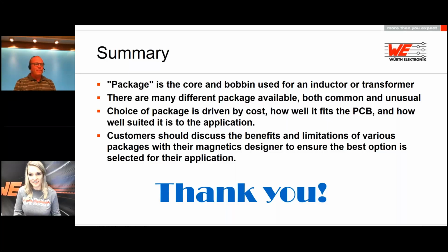I think it does. A few more questions coming in, and then we can wrap everything up. Our next question here: which does Wurth prefer for higher creepage requirements, margin tape or triple insulated wire? Now that's an interesting topic. Okay, so margin tape is typically thought of as the lower cost option, but in some cases, triple insulated wire can be a more robust solution.